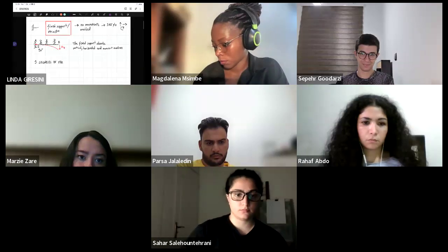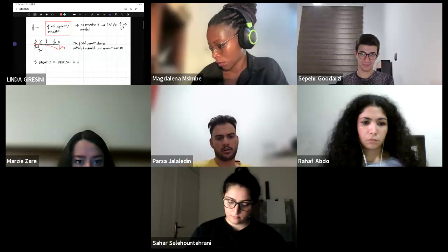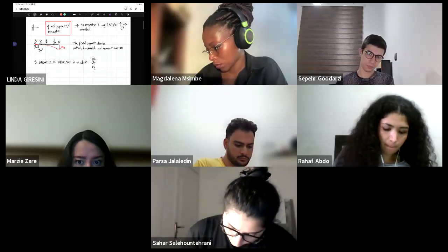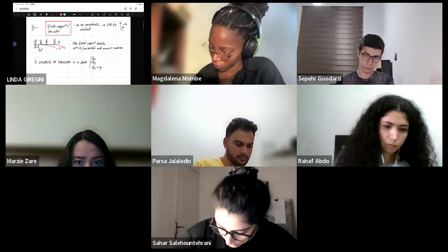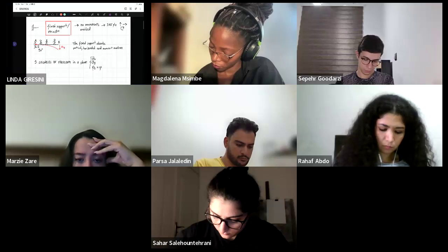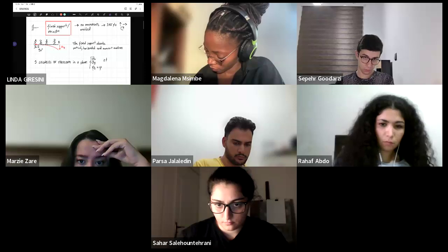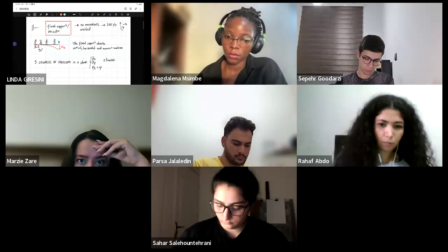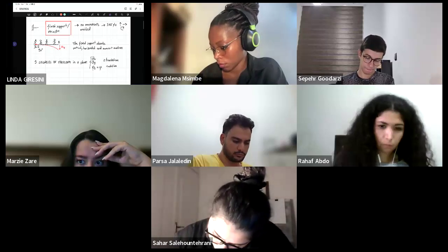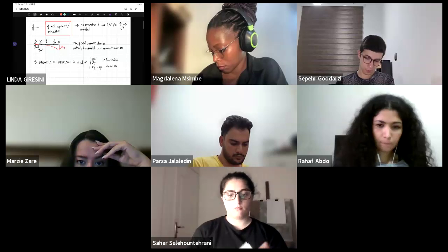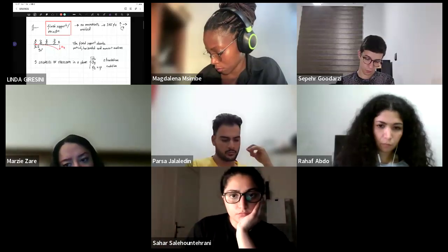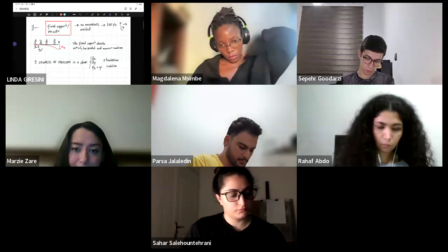3 degrees of freedom in a plane, which are the translations delta x, delta y, and phi z. Sometimes I prefer to put just phi because z is implicit. So you have 2 translations and 1 rotation. So anytime you have a body in a plane, you can have these 3 degrees of freedom. So total is 3. With these supports, remember this number 3.